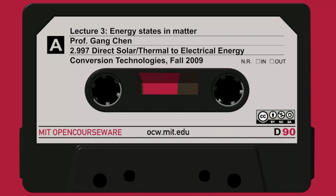And what it means is, if I give a number of dopant like phosphorus, I can see where my chemical potential is from here. Given n, I invert, I know E minus EC.